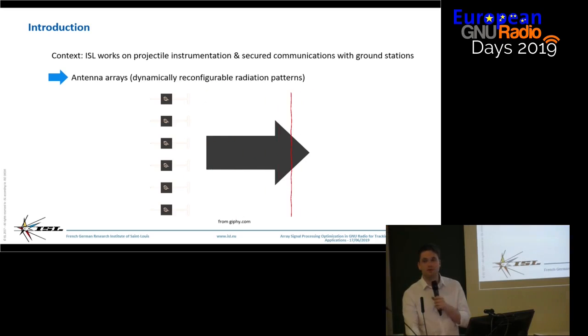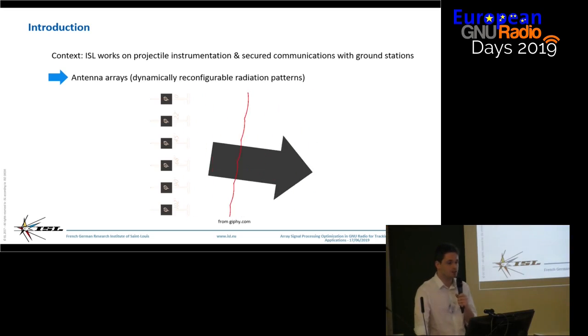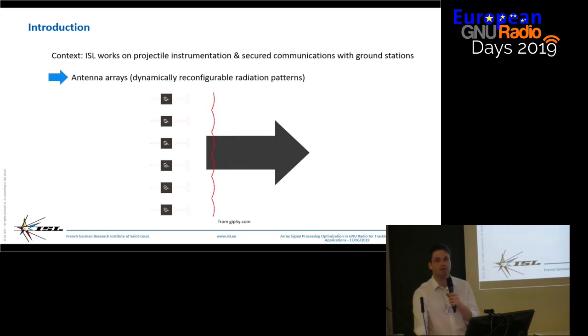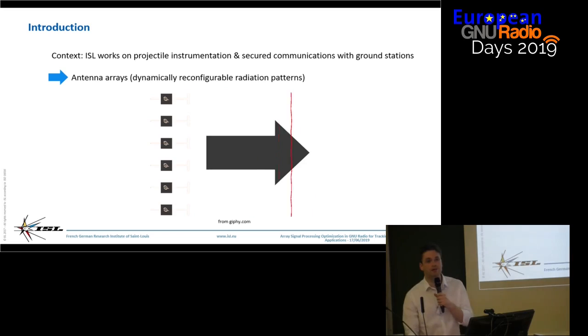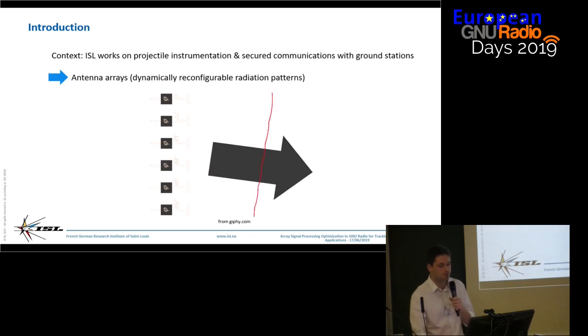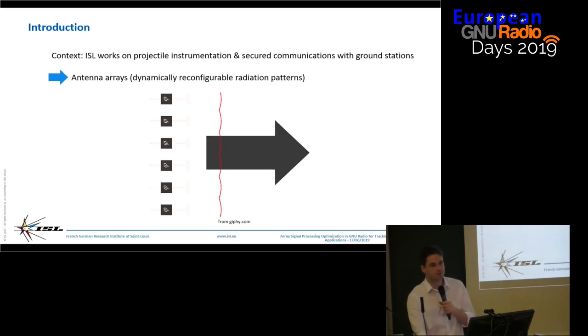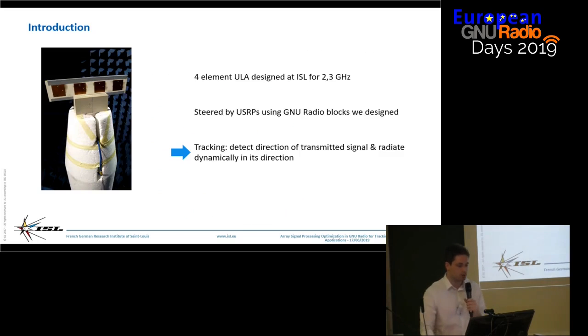But if you introduce some phase shift between your antenna element signals, then you can tilt that wavefront by a certain angle that you can control depending on that phase shift. And that's a very important property, as we will see later. That's what we're going to use.